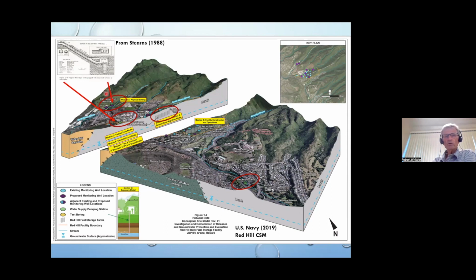To the northwest we have a primary drinking water source, and also to the southwest, a primary drinking water source. These two drinking water sources are shafts, which are basically tunnels excavated along the water table, distributing the pumping over a large area and reducing the risk of saltwater intrusion, which results in chloride fouling of our drinking water source.